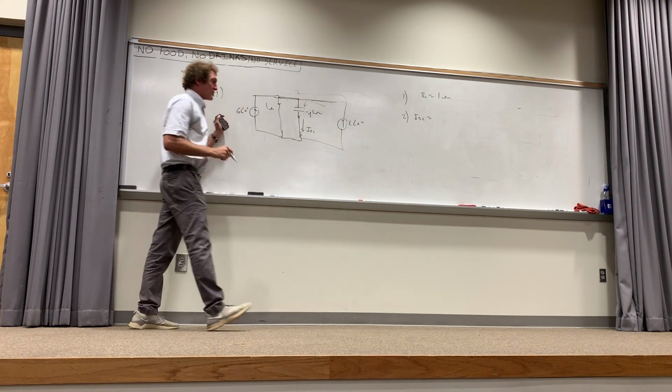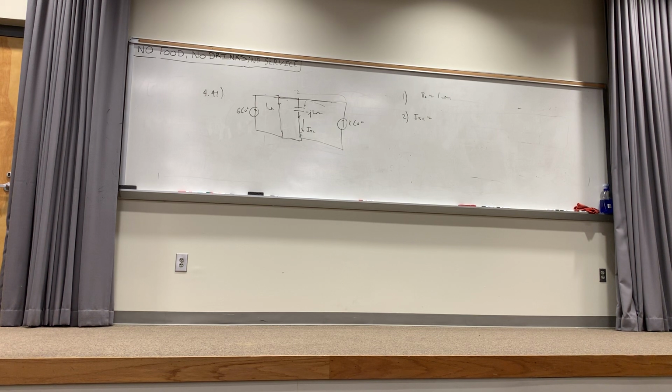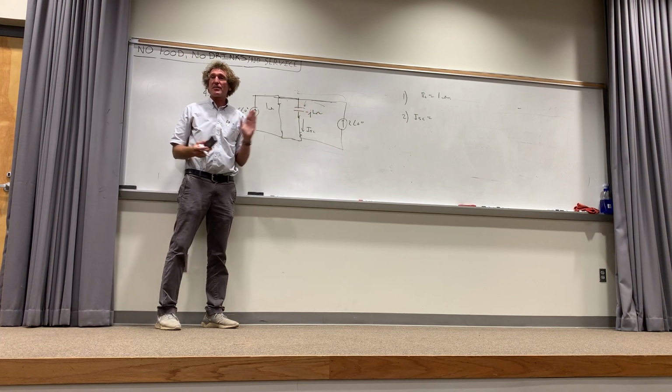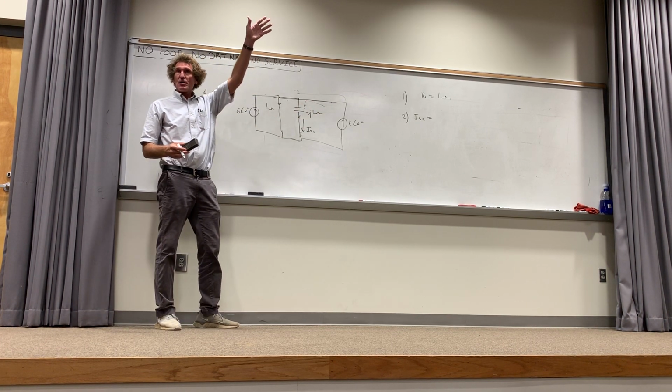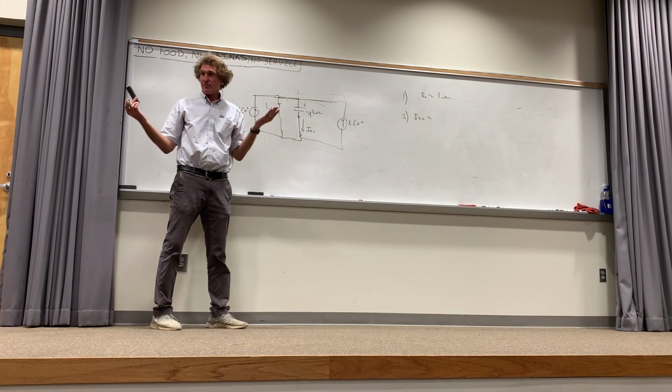And I tie that together. Y'all follow me? I'm going to see what I've done, make sure you understand. Y'all with me on that? I did a simple source transform, didn't I? In the back, you guys see this. All right, now that source transform does something really easy. It helps me because I can take the 6 and the 2 together and get a total of 8 amps flowing there. How many see that? Are you with me that you've got 6 here and 2 here all flowing to that upper rail?